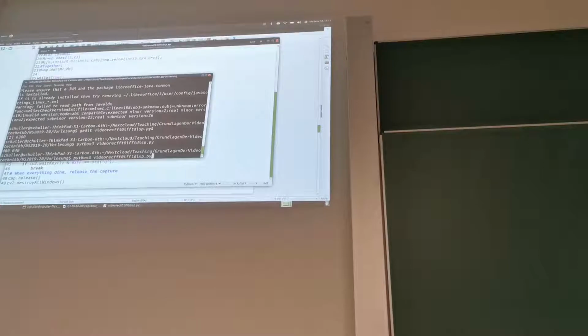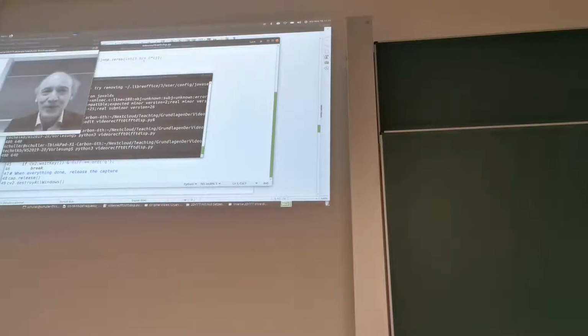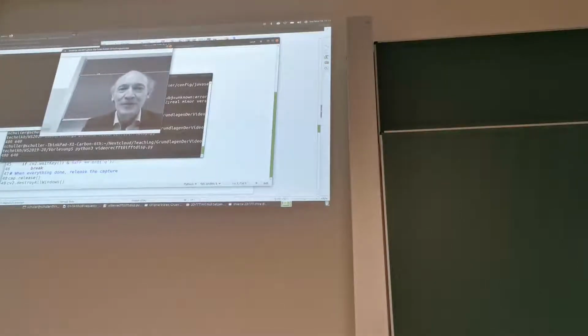Yeah, did you also see another artifact here? It's kind of interesting. When you just look at the result here, this picture, what do you think? How does it look like? Do you see those stripes here? Yeah. So these are artifacts from low-pass filtering, and they are called ringing artifacts. Because if this would be a tone audio, then it would sound like ringing, like if you hit a bell or something, right? So here, hitting of a bell is equivalent to this edge, a sudden change in brightness, and that results in those ringing, those ups and downs, near the edges.